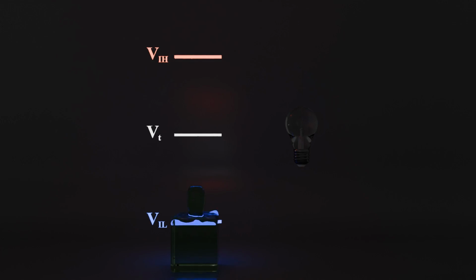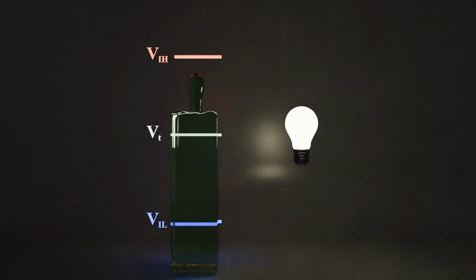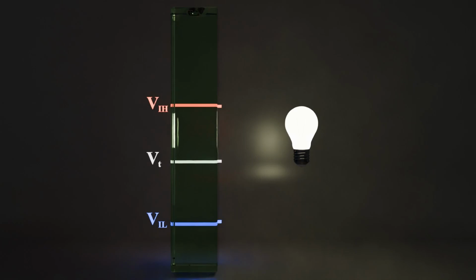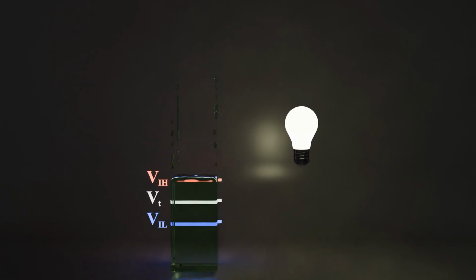As the voltage rises from VIL to VIH, there will be some point where the input is detected as a high instead, which is what we call the threshold voltage. There's still a bit of room before we get to the VIH voltage, which is the guaranteed high state voltage. So an ideal up-translation device would let you keep the same VIL, but move the VIH voltage down, giving you the ability to input a much smaller voltage and still have it get detected as a logic high.